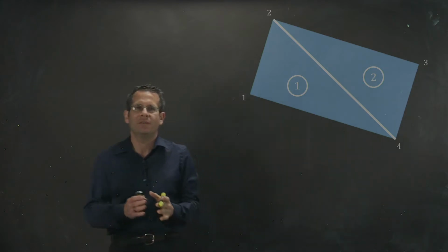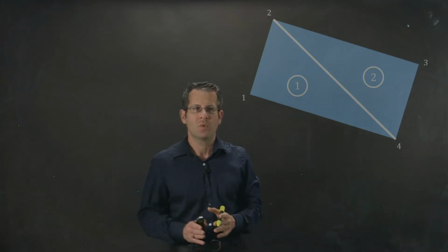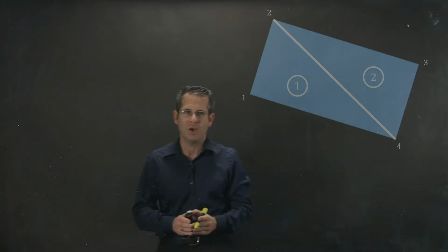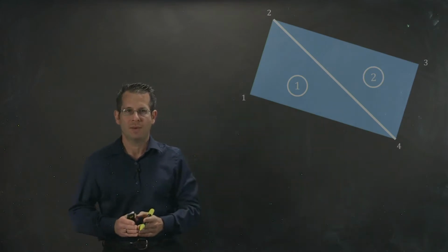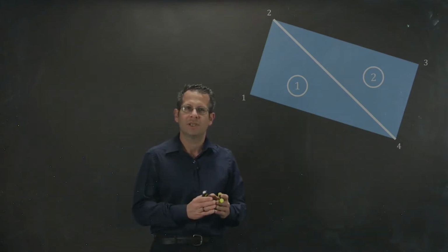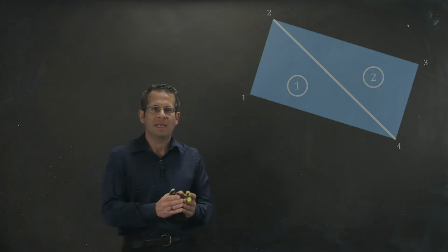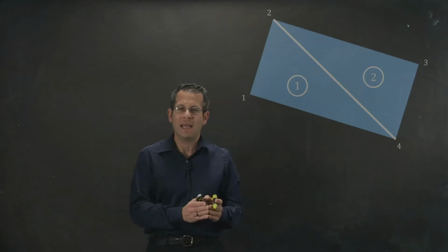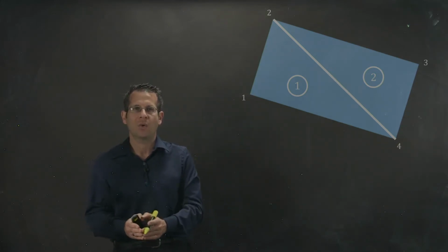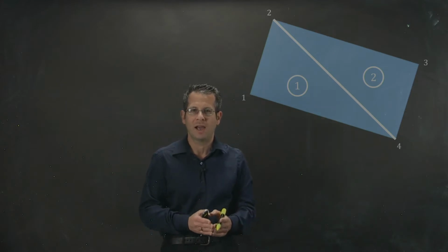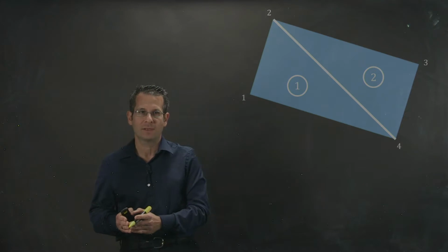In the previous videos, I've always labeled my various nodes node number 1, node number 2, and node number 3. You can think of that as a local node numbering system. It's a little dangerous to do so, but you may think of it that way. Remember, I said that it's important that I label my nodes in a counterclockwise direction, because that's how I derive the form for the local stiffness matrix.